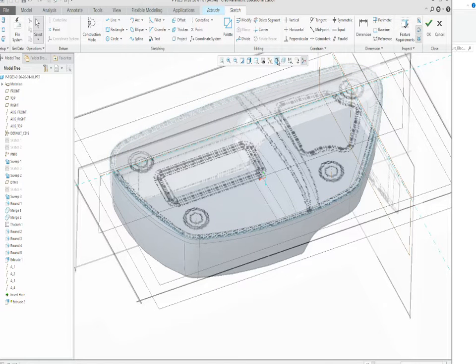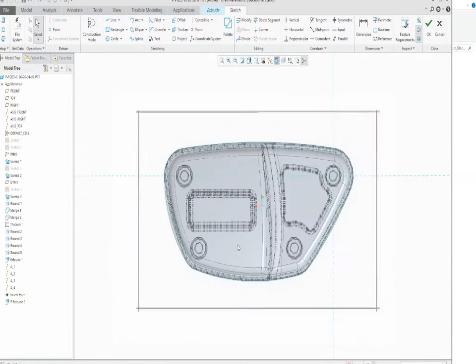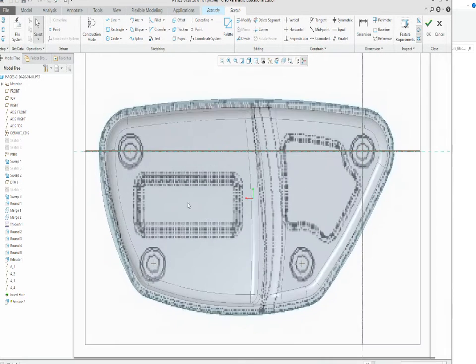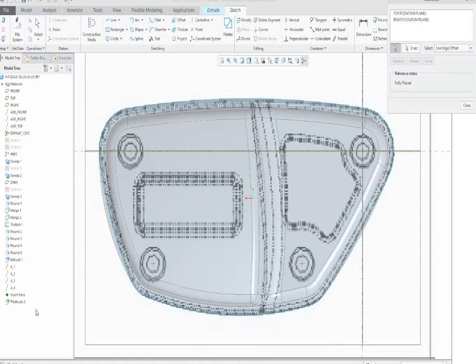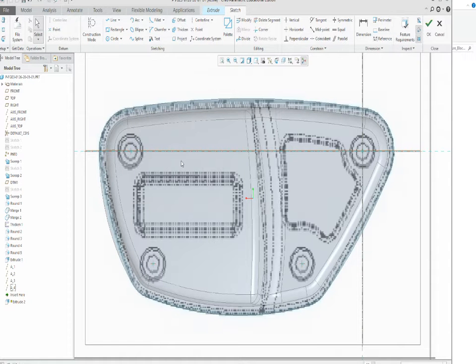When we start that extrude, we normalize, and then if we look at it, we've got the center of the hole here. So if you want to pull references, you can pull references off of these four axes that you just made. So say 1, 2, 3, 4. And that gave us a little dot to play on right there.